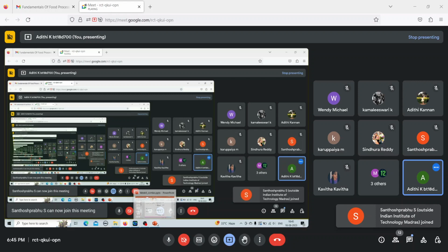So what I'm trying to say is P1 is always greater than P2, and P2 is always greater than P3. This will help the vapor to evaporate the liquid in the evaporator. So in a multiple effect evaporator, the pressure in each succeeding effect is lowered so that the boiling point of the liquid is also lowered in each effect. Hence, there is a temperature difference created for the vapor from one effect to condense in the next effect and boil the liquid in the form of vapor.